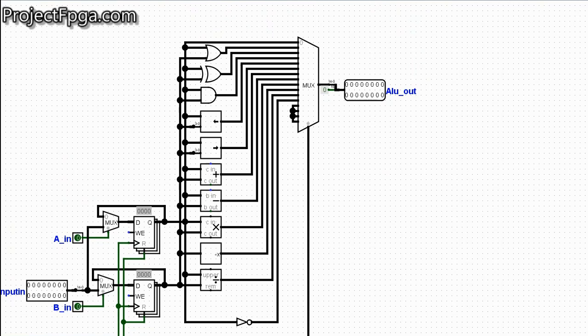First of all, I arrange all the operations according to their priority. So remember the great signal I talked about. This is where the logic comes in. The division has the highest value in the multiplexer. In case you are designing something similar, it's up to you to determine which operation will have the highest priority. So I have division as the highest priority here because it has the highest value in the multiplexer. 0 is your OR, 1 is your AND, 2 is your NOT, 3 is shift left, then shift right, plus, minus, multiplication, and the rest of them.